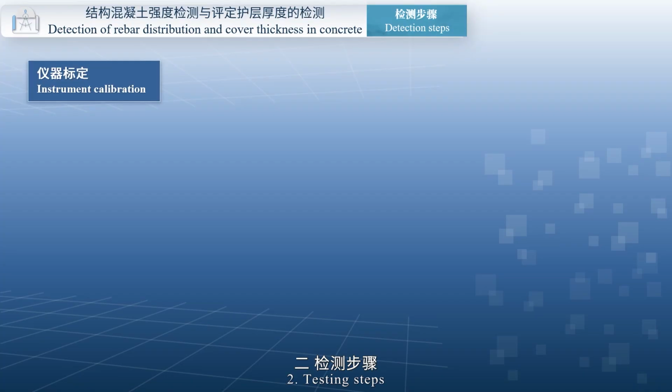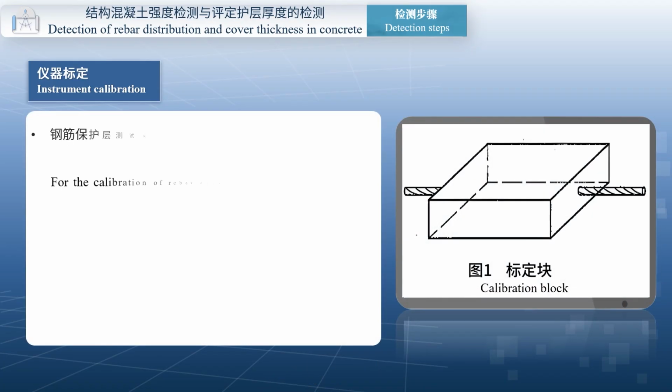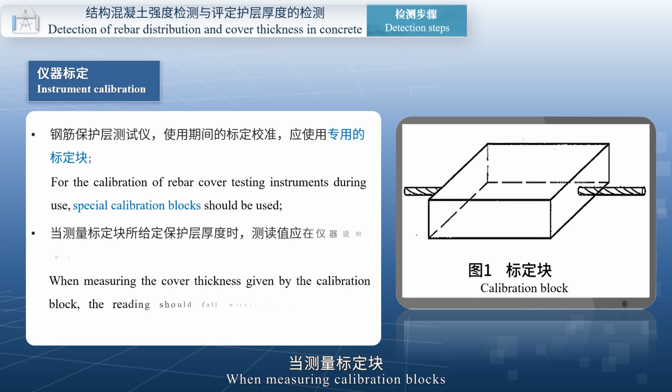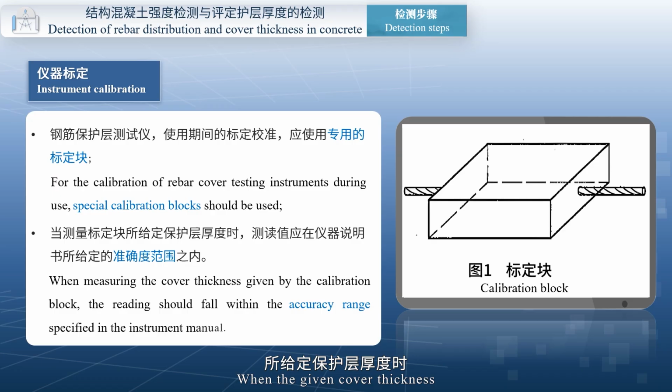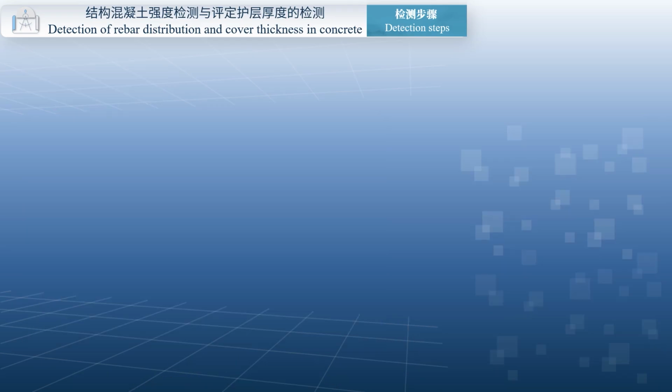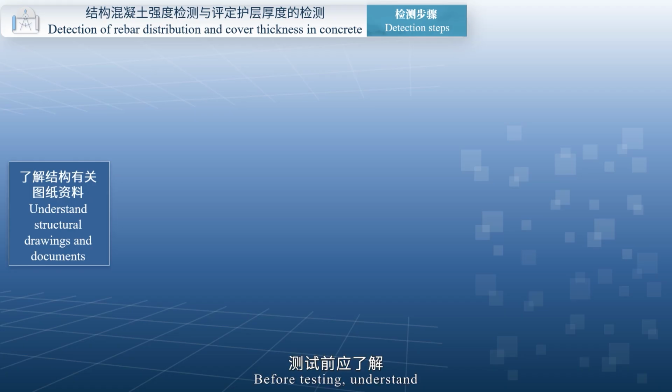Second, testing steps. Step 1: instrument calibration. The rebar cover thickness tester should be calibrated during use, with special calibration blocks. When measuring calibration blocks with a given cover thickness, the reading should fall within the accuracy range specified in the instrument manual. Step 2: before testing, understand structural drawings and documents to determine the type and diameter of rebar.